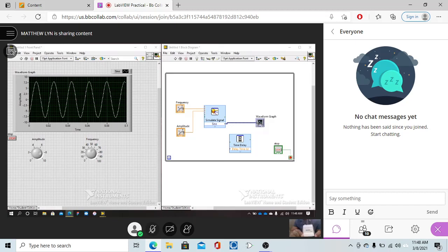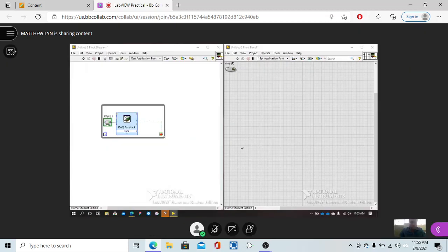So click OK and close the Express block configuration window to return to the LabVIEW block diagram. Notice that LabVIEW automatically creates the code for you for this measurement task. Click yes to automatically create a while loop. Right-click the data terminal output of the DAQ Assistant Express VI and select Create Graph Indicator.